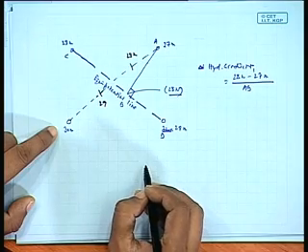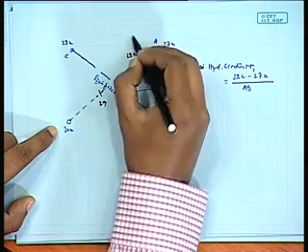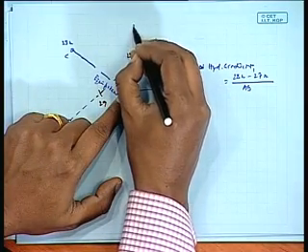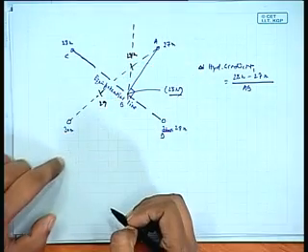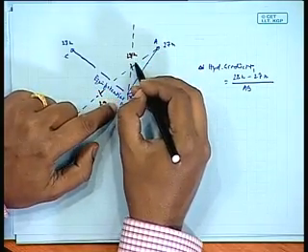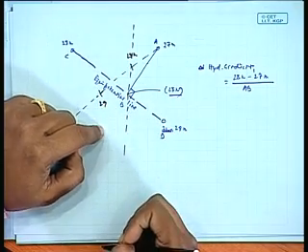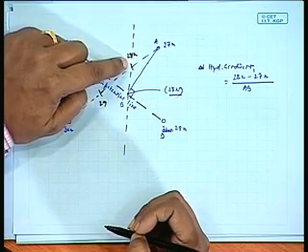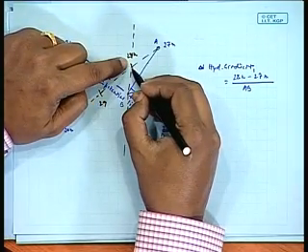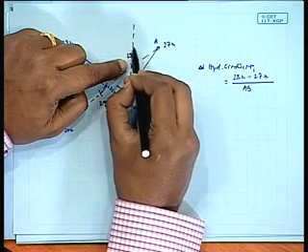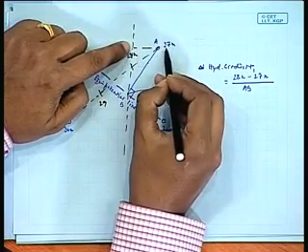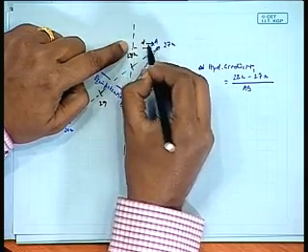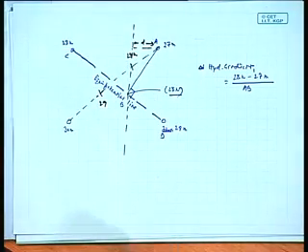In such cases, again we have to make an equipotential line from here. We can find this equipotential line like this. This one is the new equipotential line. This is 30, 29, 28 here. So we find that this is a new equipotential line. From this we will find the distance, 28 minus 27, 1, divided by this distance d, which would provide you the new hydraulic gradient.